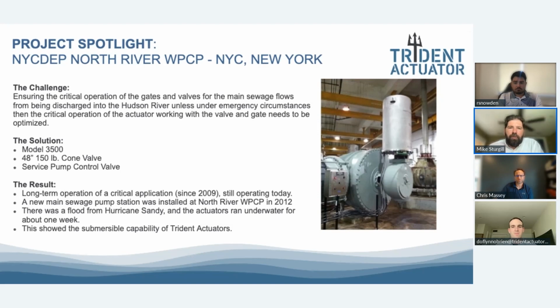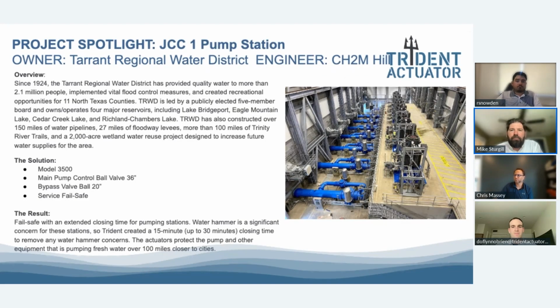Speaking of clean water, this is a nice application we have in the Dallas area where we're pumping a lot of clean water hundreds of miles away from a reservoir to the local cities there. We have our 3500 fail-safe linear on multiple 36-inch and 20-inch valves. I talked about how fast or slow you wanted us to close with the stored energy in the accumulator. Basically, they had us create a 15-minute close time to prevent water hammer. So a nice application in the Texas area.